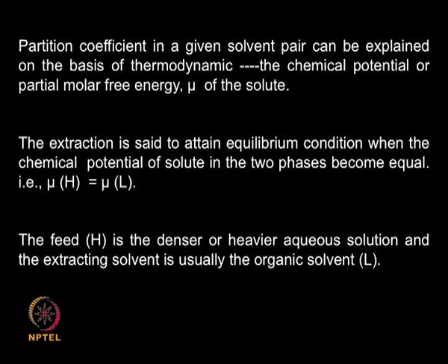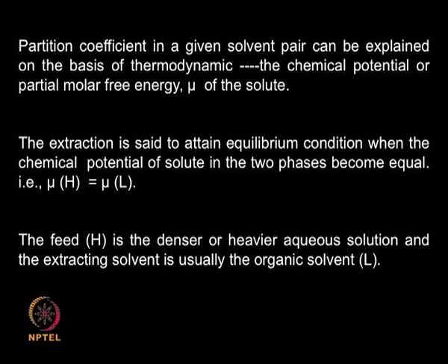So it is basically based on thermodynamics, that means it depends on the chemical potential or partial molar free energy. So the term that comes into the picture is mu, the chemical potential. So you are adding your feed and you are adding your solvent, mixing it thoroughly, and then you are separating two different streams from the stage. The two streams that are leaving the extractor are supposed to be in equilibrium, that means they attain equilibrium. So when they attain equilibrium, the chemical potential of the solute in these two phases will be equal.